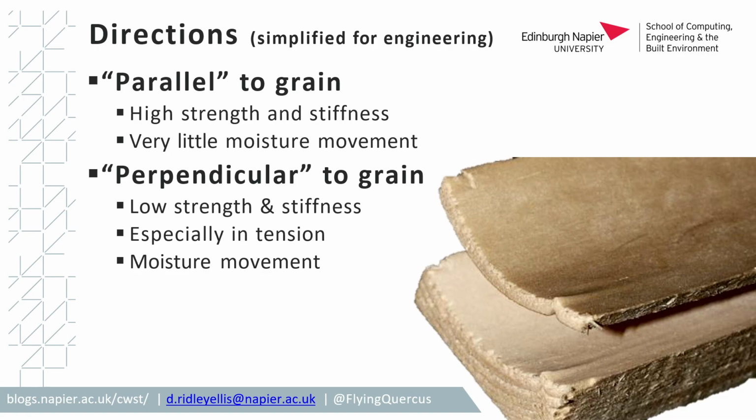But also in that end grain cut, we've got parallel to grain cutting, high strength and stiffness, very little moisture movement. Perpendicular to grain cut, low strength, i.e. it would just break. Essentially in tension, it would just pull or snap. And moisture movement is quite easy.